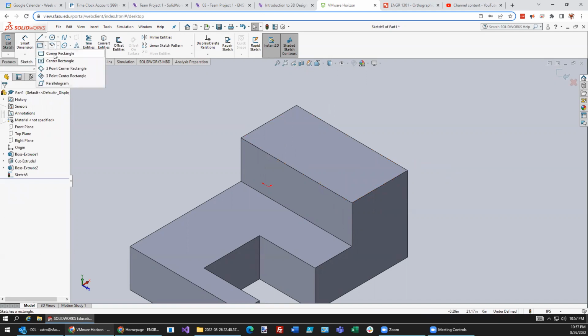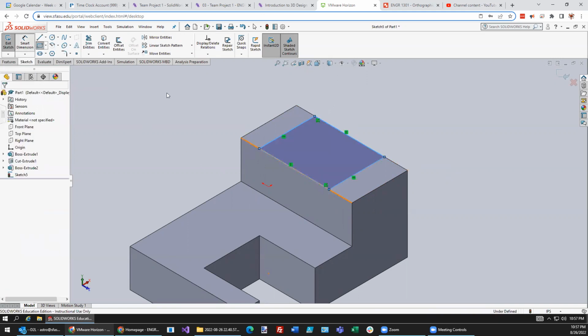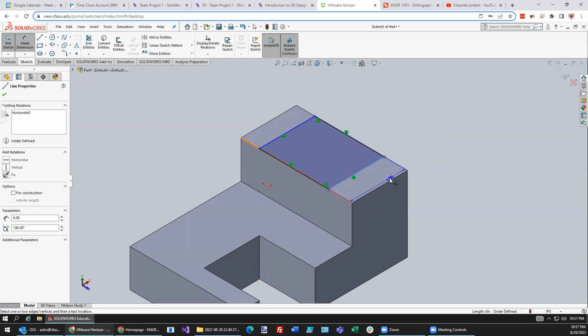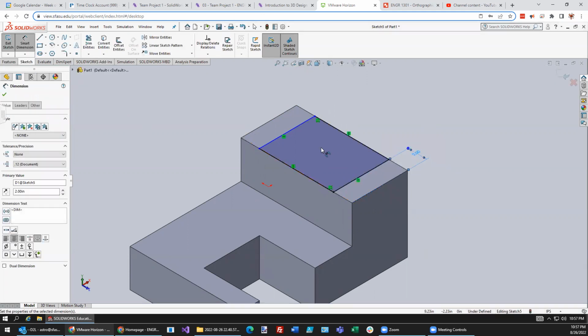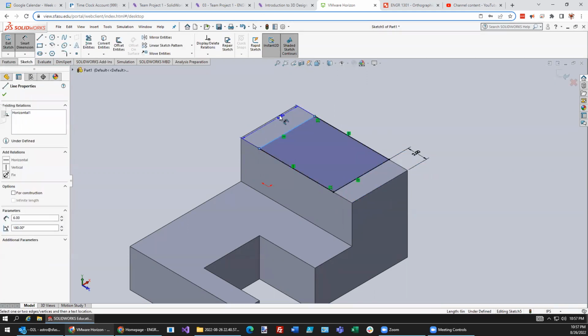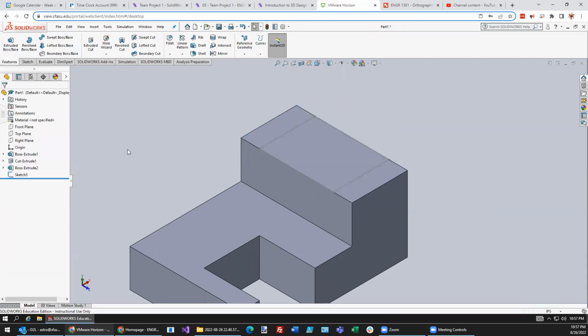And now, instead of going at the corners of that top, let's just do this and do one cut. That did not work, so I'm going to hit Escape and then try the blue and the corner again, making sure it's 2 inches from the edge. This one's still blue. It's not fully defined. And now it's fully defined. Let's go ahead and exit to begin the cut.